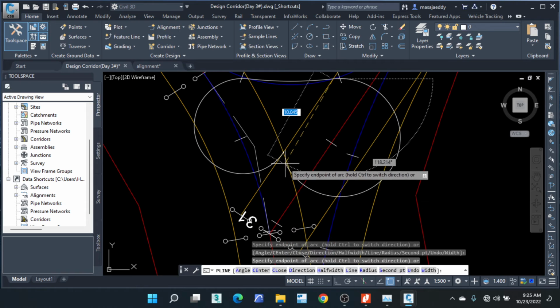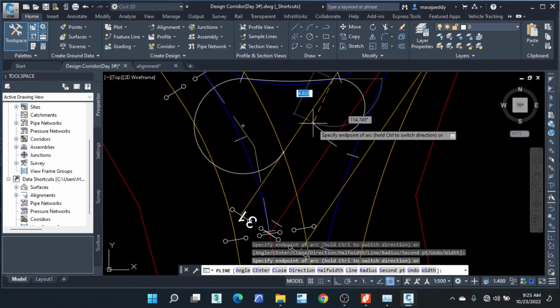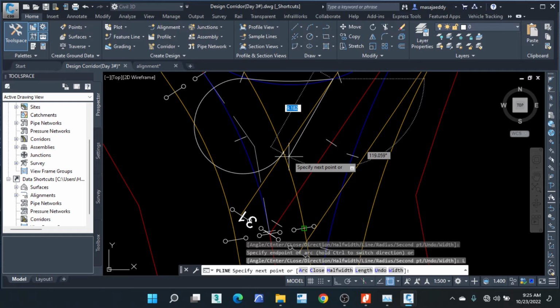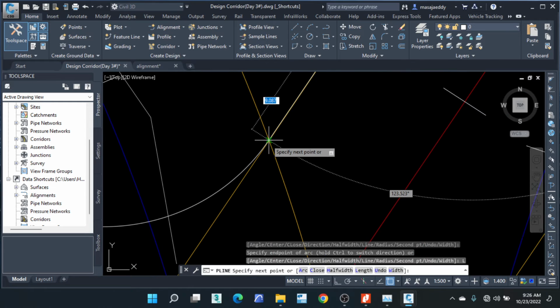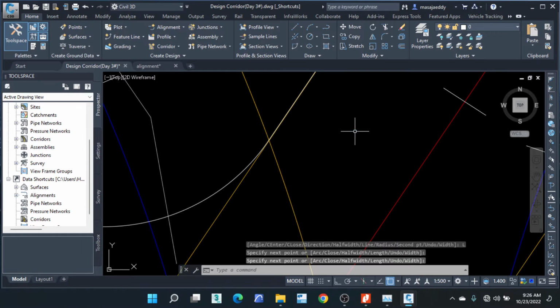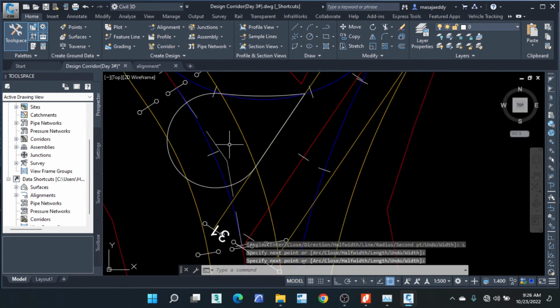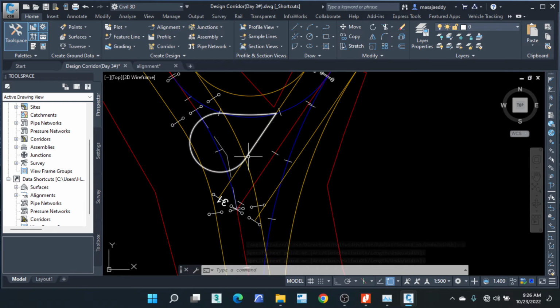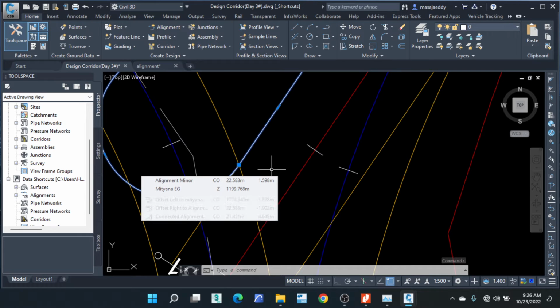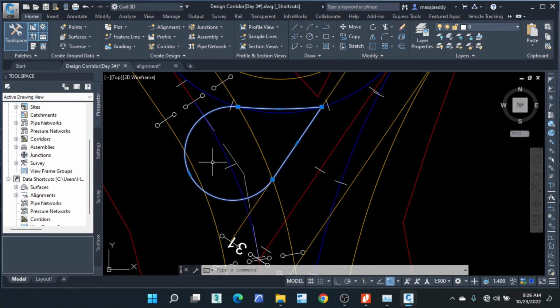Once we are done, now we need a line because this offset alignment is a straight line. So you can actually see here we have angle, center for polyline, direction, half, then we have line again. So I'm going to select line. I hope everyone has seen the line command, okay? Then you join that up to here. Once you're done, then just right click and press enter. So that now it's full. Good thing with the polyline, once you close the end to the beginning, it becomes one object. Okay? However, its other extensions can be adjustable.